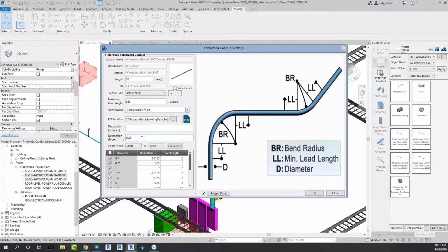Okay. So I wouldn't get too bogged down on the fact that, oh my God, I don't know what I'm buying for conduit. The point of the electrical settings is telling SysQue how often to break that conduit and put couplings in there. All right. And you don't have to do this when you initially draw. You can do it later on.